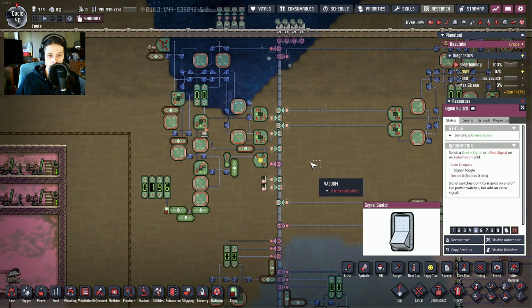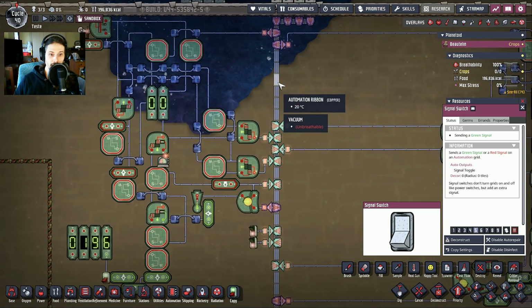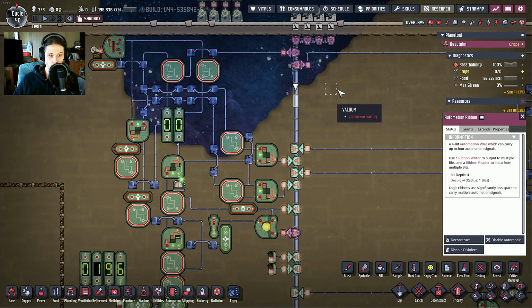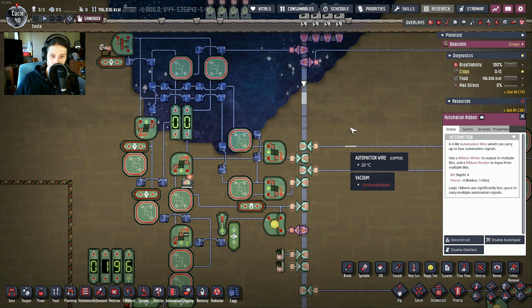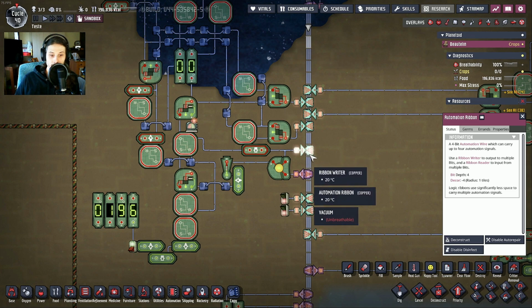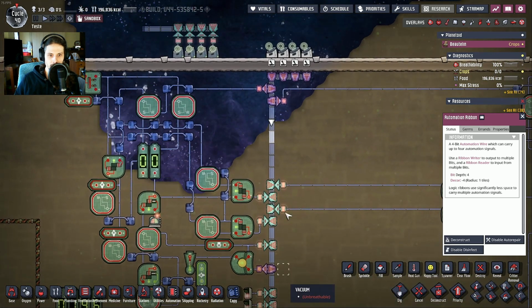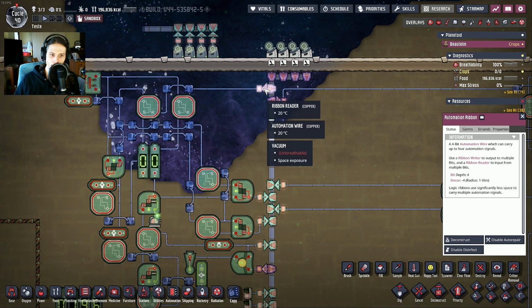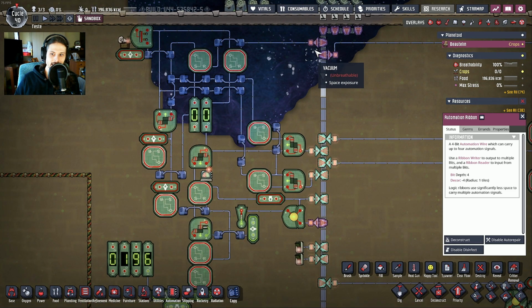We have multiple things that prevent writing at the same time. This is why we only have 2 digits for our codes, because we need all the 4 bits of the ribbon for this to work. Bit 1 and bit 2 are the code. Bit 3 is the busy line. This bit tells all the encoding systems that the line is busy and is being written upon, so the other encoding systems don't write into the line at the same time, creating massive confusion. And then you have bit 4 over here, which is the confirmation/reset of the entire system. This is the signal or pulse that is going to tell the encoder system that the signal was received, allowing it to reset.